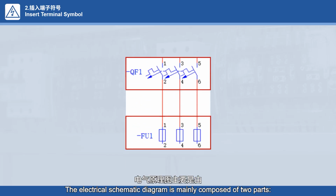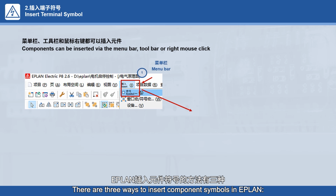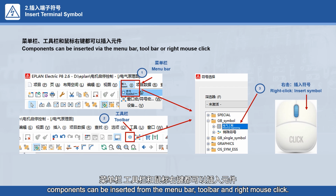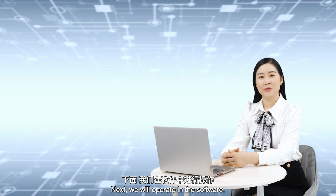The electrical schematic diagram is mainly composed of 2 parts: electrical component symbols and wires. Most wires are automatically generated after the electrical components are inserted, so it is necessary to insert the component symbols before drawing the wires. There are 3 ways to insert component symbols in E-Plan. Components can be inserted from the menu bar, toolbar, and right mouse click. You can choose according to your own habits and preferences. Next, we will operate in the software.